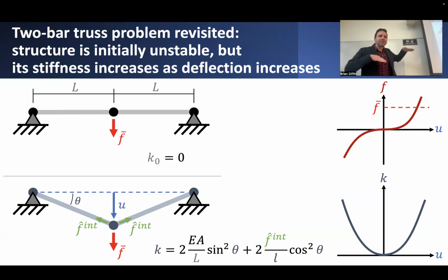So the increase in force will be basically flat relative to small changes in U. But as you increase that transverse deflection, the resisting force starts to go up. And it doesn't matter if you're pushing down or pushing up, it'll start to increase in either direction. And it'll continue to increase until it matches whatever applied transverse load we put on this cable.